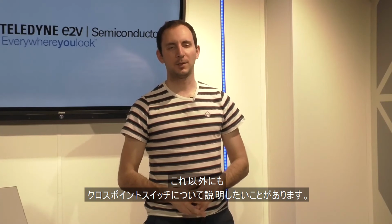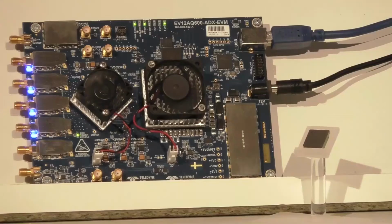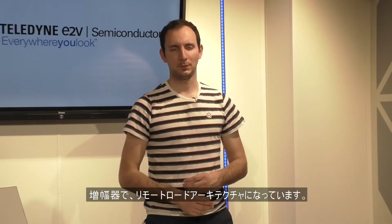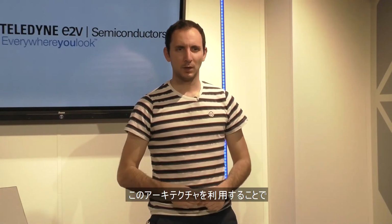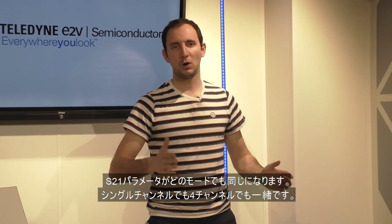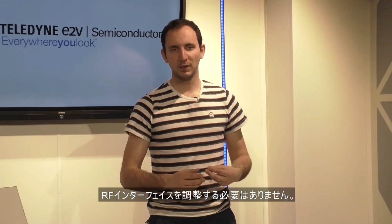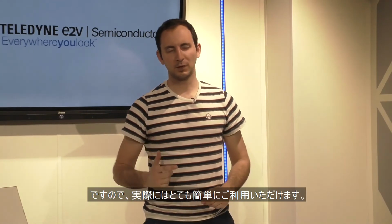There's something else that's special about that Crosspond switch. It's its architecture. It has an open amplifier with remote load architecture. So you might wonder, how does that make my life easier? Well, thanks to this architecture, the S21 parameter is the same whatever the mode, 1, 2 or 4 channels. It means that when you change mode, you don't need to adjust the RF interface because the chip behavior will be exactly the same. So that's what makes your life easier.